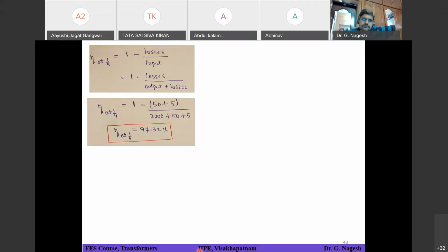So we have to find the efficiency. What is the copper loss at half of full load that you said first? Copper loss at half of full load is 20 watts. Okay. So what will be the output at half of full load? 4000 watts. Okay, so now you calculate the efficiency. 98.28 percent. Okay, so 98.28 or 98.3 approximately.